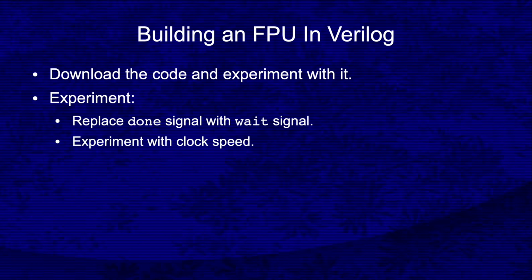The current system clock is running at 1 Hz. This is artificially slow so that we humans can observe as each bit of the quotient significand is computed. You might experiment with how fast the system clock can be made to run and still have the circuit produce correct results. Along those lines, you might test whether computing each bit of the quotient is slower than the rounding of the significand. If rounding limits how fast the clock can run, then it might be possible to compute 2 bits of quotient per clock cycle in the first part of the state machine and still achieve better performance.